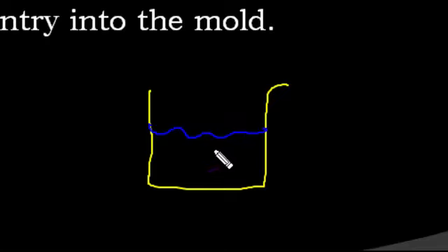Now, if it is forming some small bubbles which are trying to escape, and at the same time the surface layer solidifies, that means the simultaneous nucleation of the solid grain, the solidification nuclei, and the gas bubbles are forming simultaneously. So gas bubbles are just about to escape, but the solidification nuclei prevent the escaping of the gas bubble. So it results in formation of a porosity that is seen immediately below the surface.